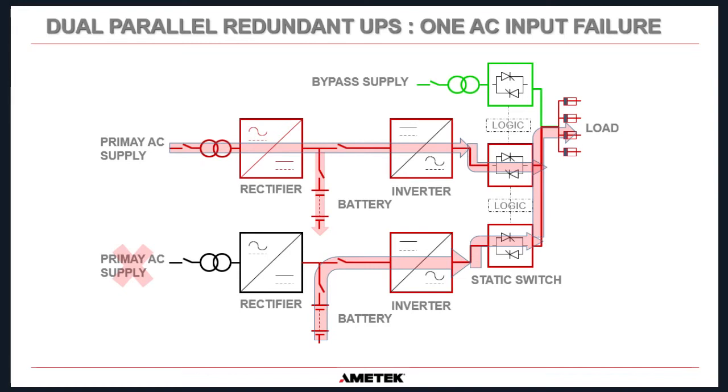You'll get an alarm on this UPS to tell you you are in battery operation. But the outputs of both UPS systems will still be connected in parallel through the static switch, and the loads won't see any issue with this whatsoever. Okay.